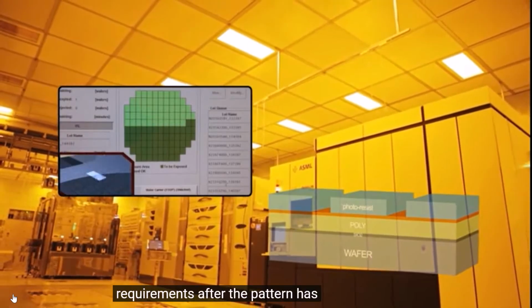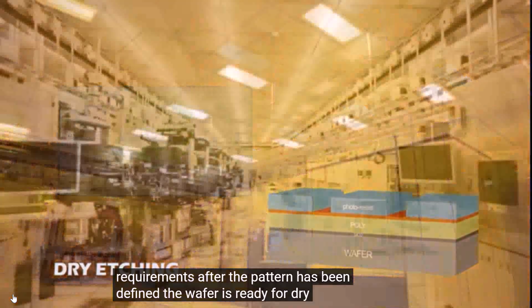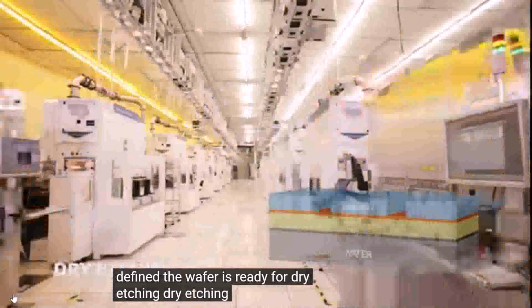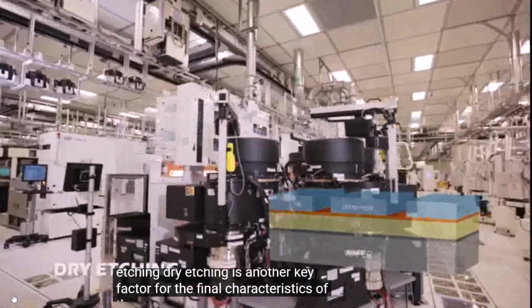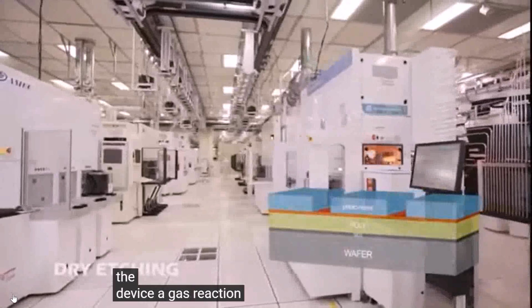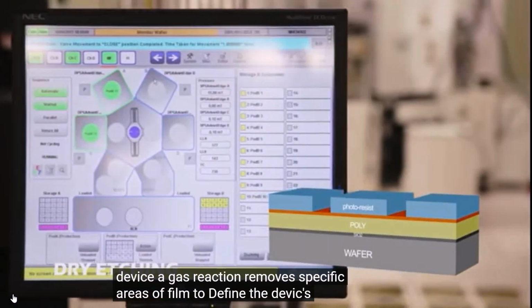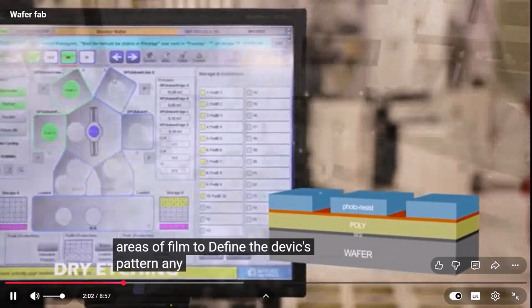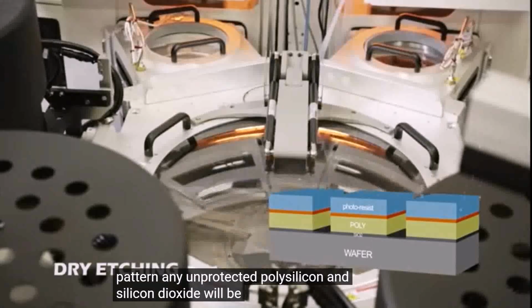After the pattern has been defined, the wafer is ready for dry etching. Dry etching is another key factor for the final characteristics of the device. A gas reaction removes specific areas of film to define the device's pattern. Any unprotected polysilicon and silicon dioxide will be removed.